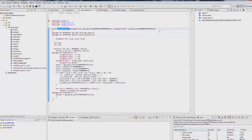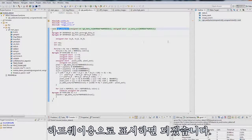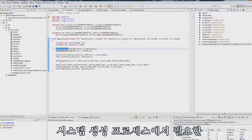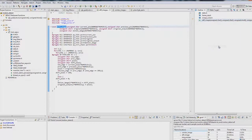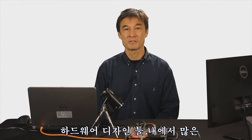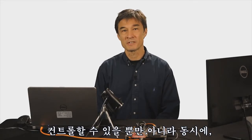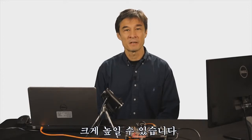In SDSoC, we specify functions to run in hardware by selecting them in the IDE and marking them for hardware. With this simple gesture, we instruct the tool to make all of the necessary changes in underlying compiler and system generation processes. Moving a single function from software to hardware usually requires many steps within software and hardware design tools. With SDSoC, you still retain control over every key design decision, but the tools handle many of the time-consuming and error-prone operations, thus dramatically increasing your productivity.